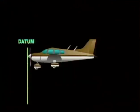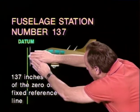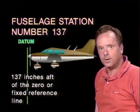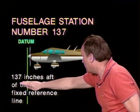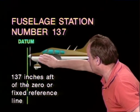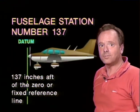Now let's go back to that concept of fuselage station and ask you, what does it mean if you're at fuselage station number 137? Well, what it means is you're located 137 inches aft of the datum line. Now on the test they don't call it the datum line. It's 137 inches aft of the zero or fixed reference line, and that's fuselage station number 137, really 137 inches aft of the datum line.